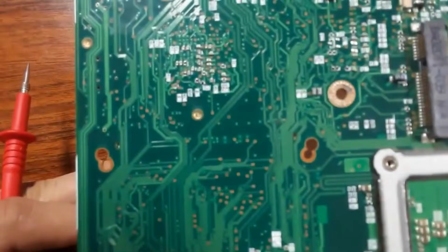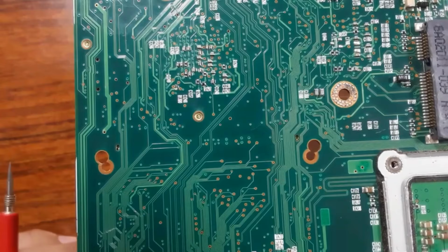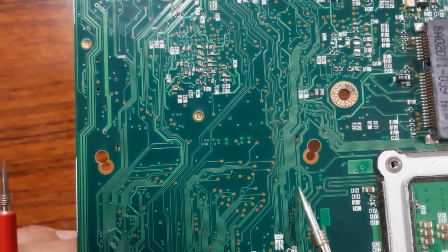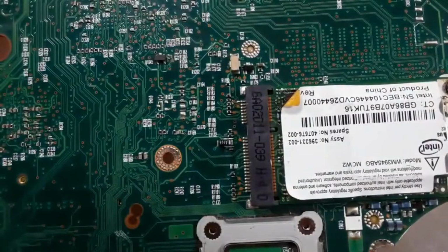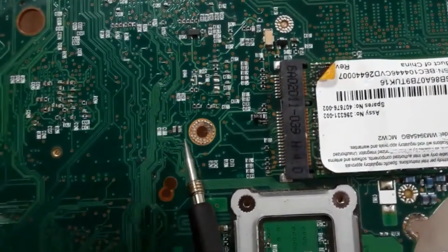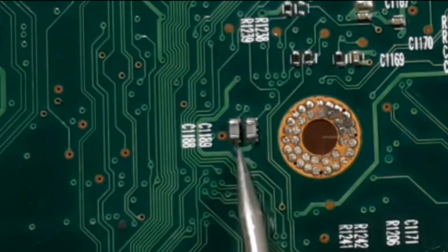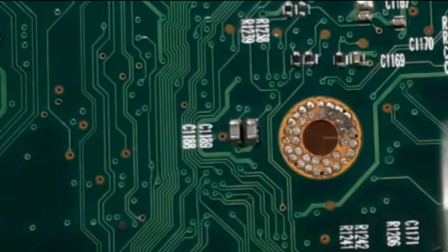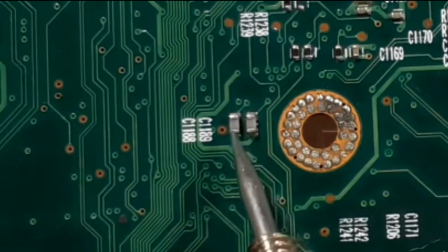Do you see here in the motherboards? All these are buses. Okay, all these are buses. You can use these buses to know the connection between the components. For example, if you look at these 2 capacitors, these 2 capacitors are connected together, as you can see here. Why? Because we have this bus here that connects between them.